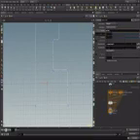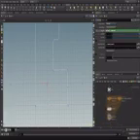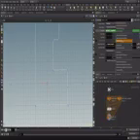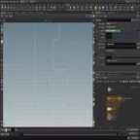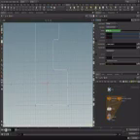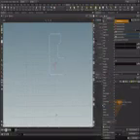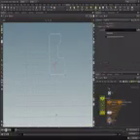Let's reference our null node, which is also called n prims. And there we go. But this won't work yet in a compiled loop because we need a spare input. So let's add a spare input, and then this line we're gonna do Ctrl X and place -1 here. And then over here I'm gonna paste it and remove those two to make sure it still works. Voila, it still works. And then we can place down a compiled block.